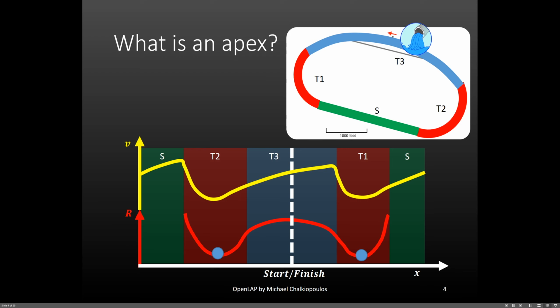But what happens in a dry race when a car blows its radiator and pours coolant all over the start-finish line? Well, then the cars on slick rubber would have to brake and drive through the wet surface slowly to not overshoot and hit the wall. This means that the velocity trace would be modified and look something like this. And this illustrates the problem I'm trying to explain very well, as a new apex appears out of nowhere on the start-finish line even though there are no curvature local extrema at that point. So there is something more to this.